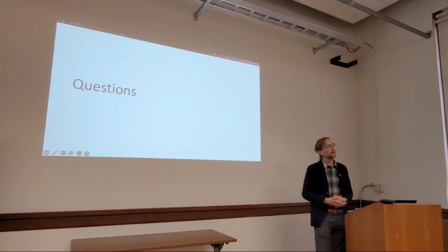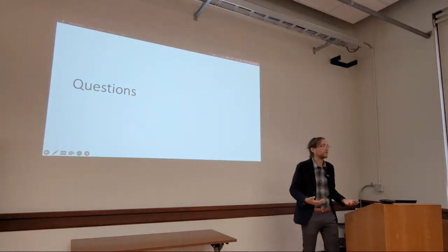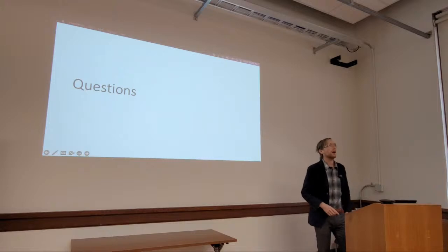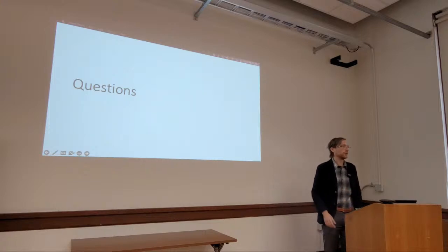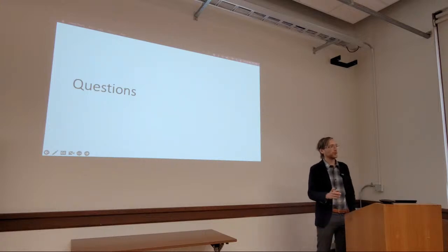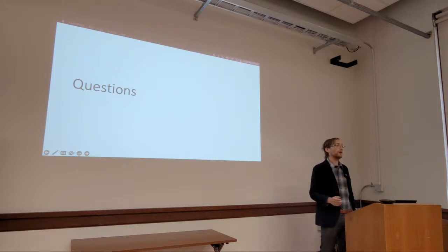Yes, so there's a finite number of directions these modules can take because they correspond to the symmetries of the dodecahedron. So I represented them with integer variables. And in fact, I didn't even consider all orientations because I ruled out directions that result in a negative thrust, because it wouldn't make sense to have that. So I only consider a rotor pointing up, or 3 possible directions for the rotor being tilted. So there are 4 possible directions of the rotor, and also 2 possible rotation directions of the propeller.